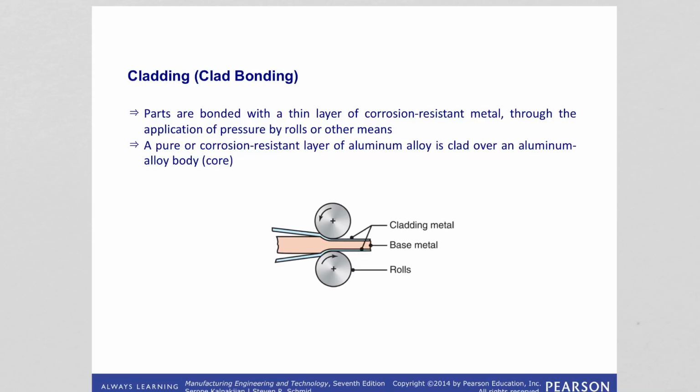We can take cladding of aluminum as an example. Here surface layers of weaker but more corrosion resistant single phase aluminum alloys are applied to a base of a high strength but less corrosion resistant, age hardenable, stronger aluminum alloy core. Stainless steel can also be used to clad steels, reducing the need for nickel and chromium alloy additions throughout.